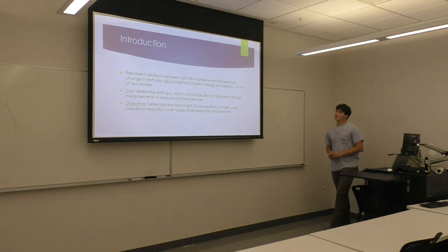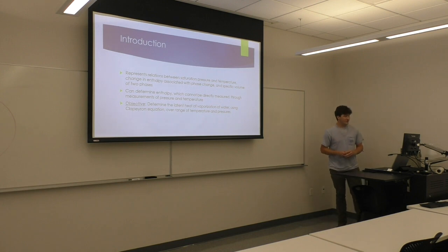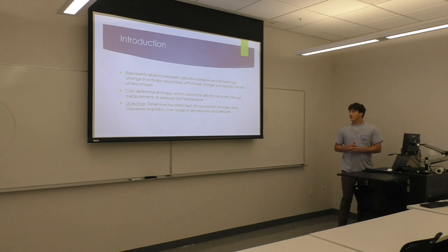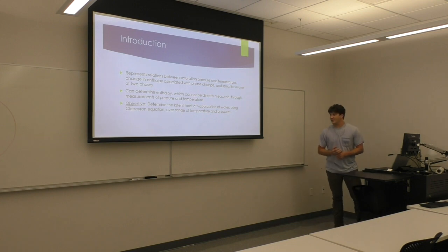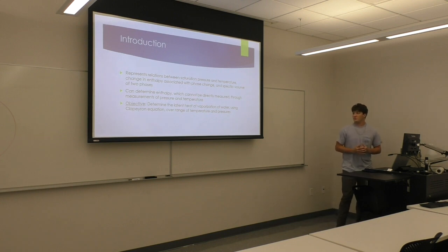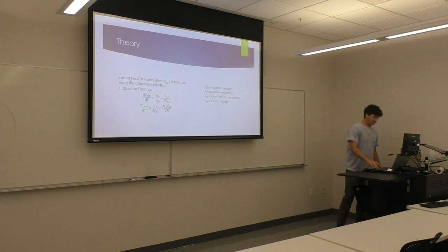Little introduction. The purpose of the experiment is it represents relations between saturation pressure and temperature, the change in entropy associated with phase change, and the specific volume of two phases. We can determine the enthalpy through measurements of pressure and temperature since it cannot be directly measured. And the objective of this experiment is to determine the latent heat of vaporization of water using the Clapeyron equation over a range of temperatures and pressures.